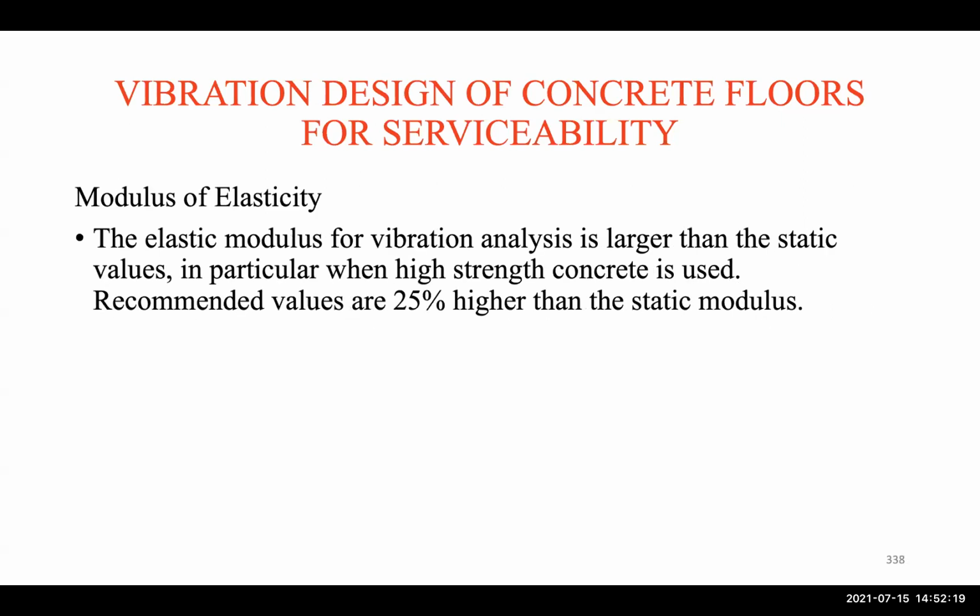The modulus of elasticity: we know how to calculate the modulus of elasticity of the concrete floor, right? Now, the elastic modulus for vibration is larger than the static modulus, E sub c, which we know, especially for high strength concrete. Therefore, it's recommended to use a 25% higher modulus of elasticity than the static modulus. So you find Ec and then you multiply it by 1.25, so that's your E.